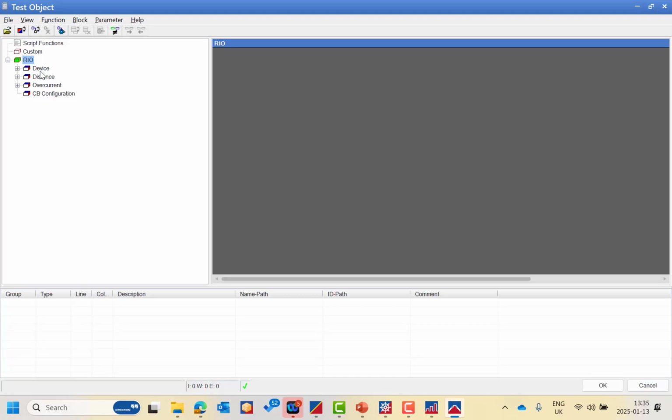You can use your time to customize your test template instead of starting from scratch. This is made for you, free of charge. You can use the benefit of this. Just import the relay settings. After that, start to remove and add test modules based on what you need. It will save all of your time. Instead of calculating everything, it will be automatically calculated.